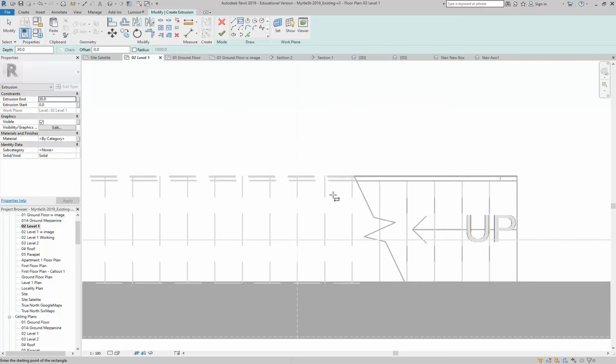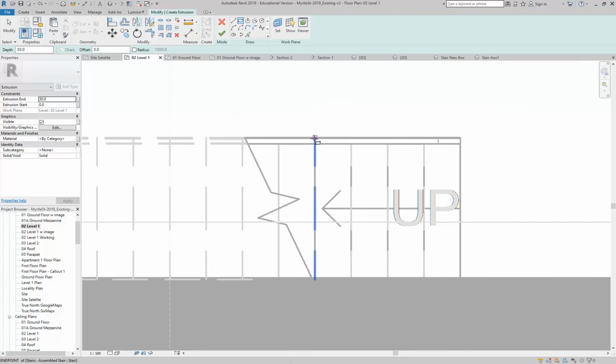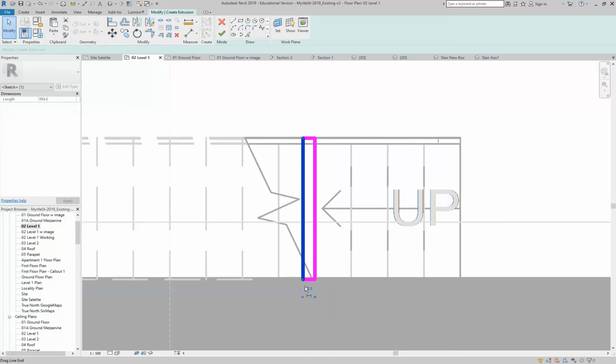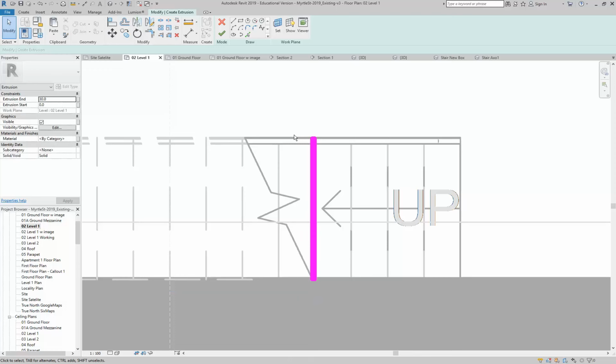So I'm going to draw a rectangle maybe over one of these risers and just bring it out from there. And then I can come back and select one of the sides and change that to 20. So that's going to give me my vertical pieces. And then I'm going to just put in a height, just guessing, might say that's about 1 metre, 1,000.